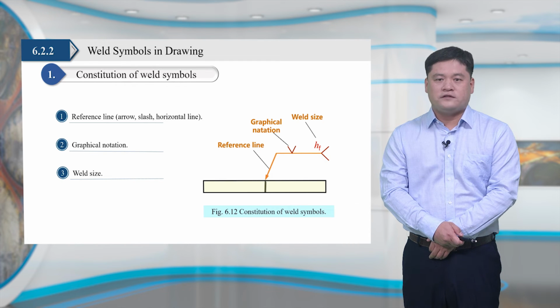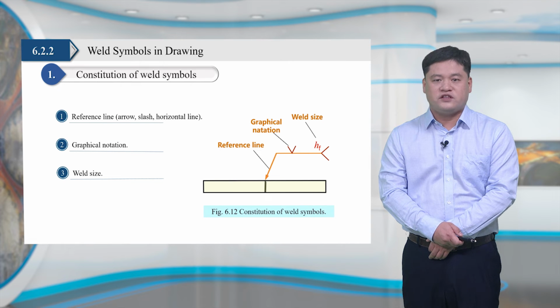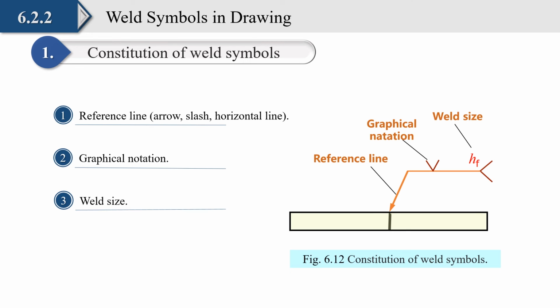In designing drawings, welds are described by special symbols, providing information about the weld's position, size, and configuration, etc. A standard welding symbol is generally composed of basic symbol and guideline, and supplementary symbol and weld size if necessary. The basic symbol represents the cross-section shape of the weld, including fillet weld symbols and groove butt weld symbols.